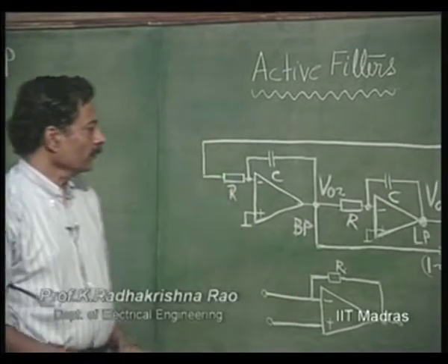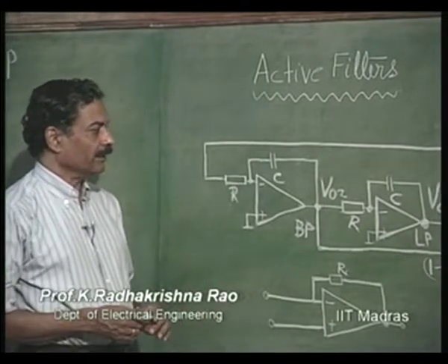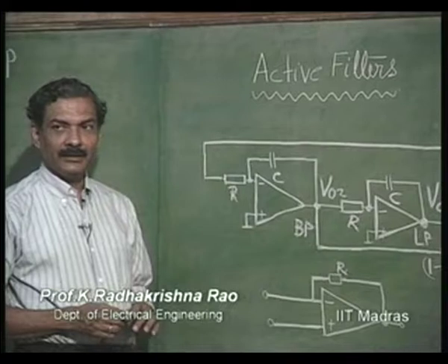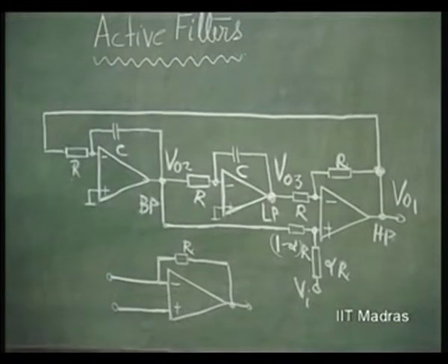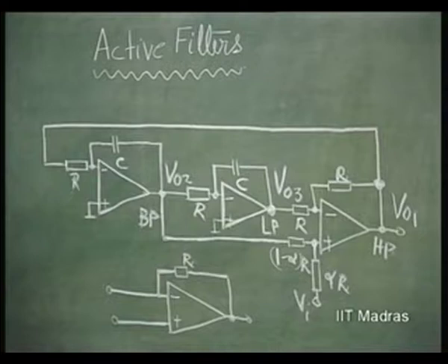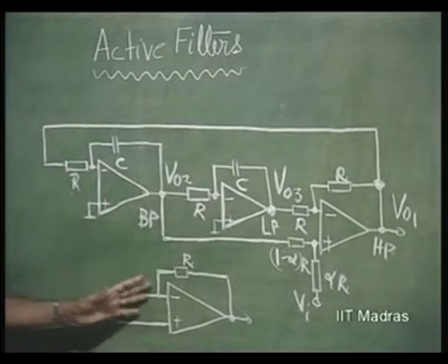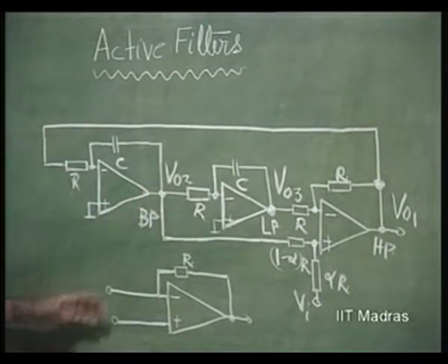So, we had discussed this circuit, we had even synthesized this circuit. This is the circuit that simulates a second order differential equation, and it is also called Kelvin-Huelsmann-Newcomb network or universal active filter, and this is available as an IC with 4 op amps inside.